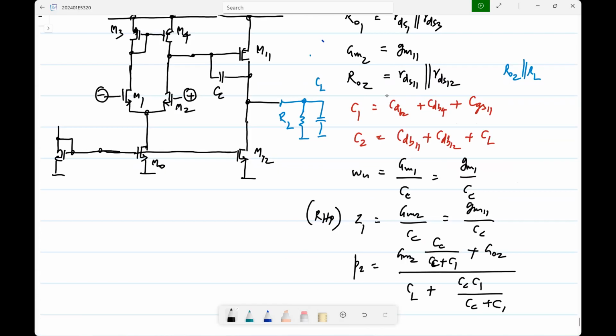You follow the single-stage op-amp with a common source amplifier with an active load, and you have the two-stage op-amp. Because we have good understanding of this op-amp at the control source level, if you want a certain unity gain frequency with a certain load capacitance, which is typically what you will be asked to do, you will be asked to drive a certain load, could be CL or CL plus RL, with a certain bandwidth.